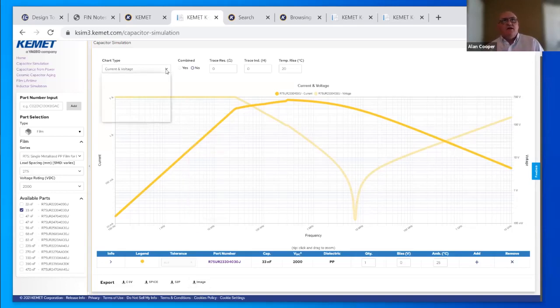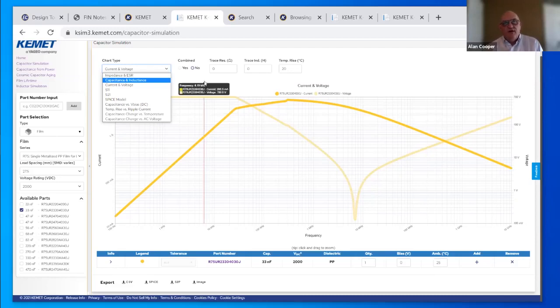The next thing we'll look at, let's go down there. We talked about the S1 and S2 parameters. I'll talk about the other one. There's an S2P download there. What that does is it basically downloads the S parameter model, if you're familiar with those, and what they will do for you. That's also available. It's a common standard these days in the industry. So if you need those models and you work with them, you can actually get that as well.